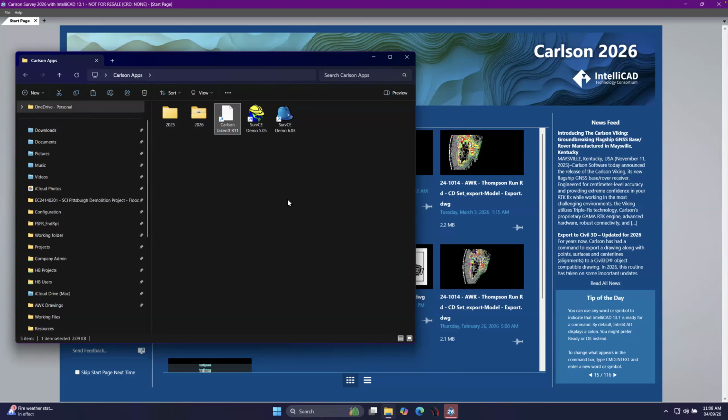And then once those surfaces are built, they can be transferred to machine control, so it can go out there and get those surfaces. You excavate down to your subgrade, and there's two different approaches to that. Two different approaches in terms of machine control or automated machine guidance, AMG, you might see it called sometimes.